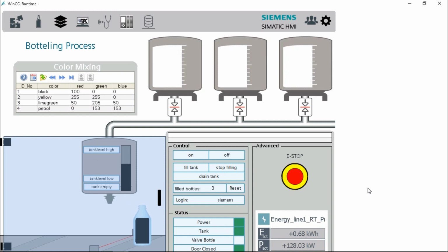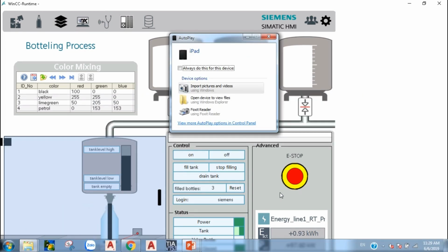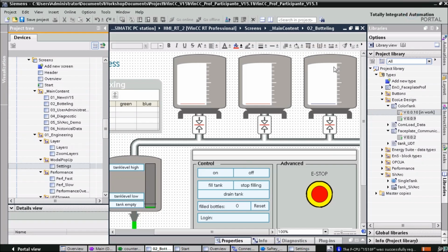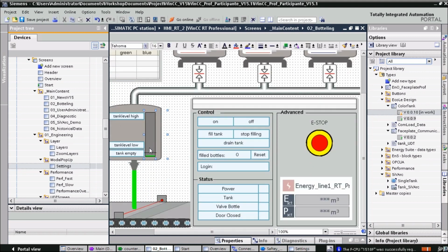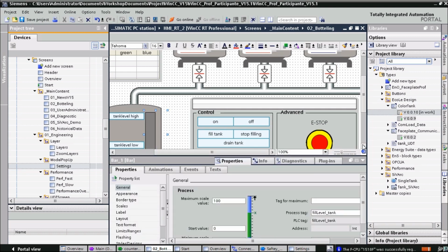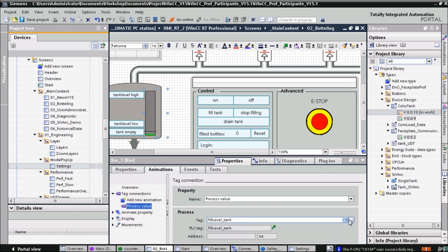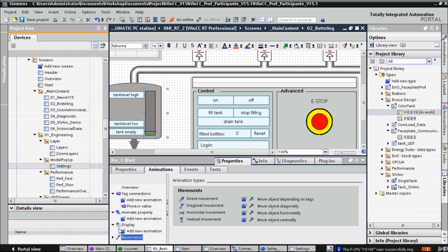Okay, just to switch back to the engineering itself, when I select my faceplate again, how should it look after I've rolled out the linking to all of the 3 tanks? My valve status is actually my symbol of the valve. So when I switch to the faceplate itself in the library management, to show you this really quick, what's behind the logic is basically this graphic I/O field.